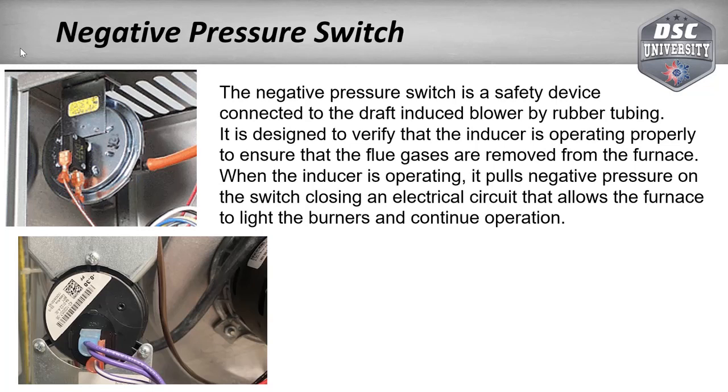So it's very dangerous. Now, because the pressure switch is wired back to that circuit board, the circuit board has logic built into it to where it knows that pressure switch has to be open before the cycle starts, and then it closes after the cycle starts. So if that board sees that somebody's jumped that switch out, it'll throw an error code that won't allow the furnace to run. So they have that safety built into the logic of the control board.